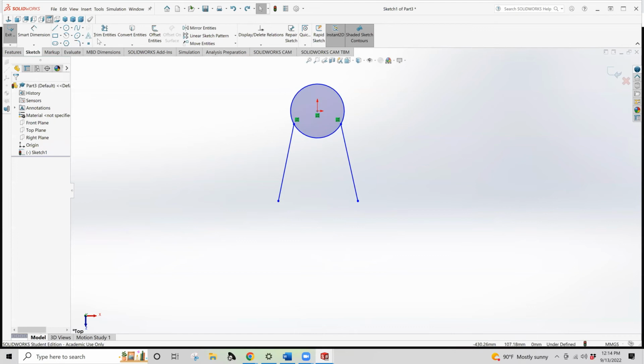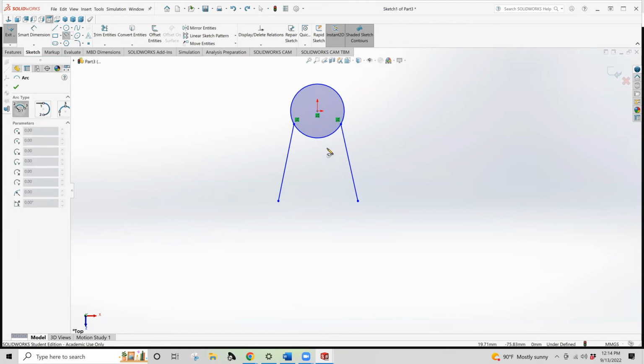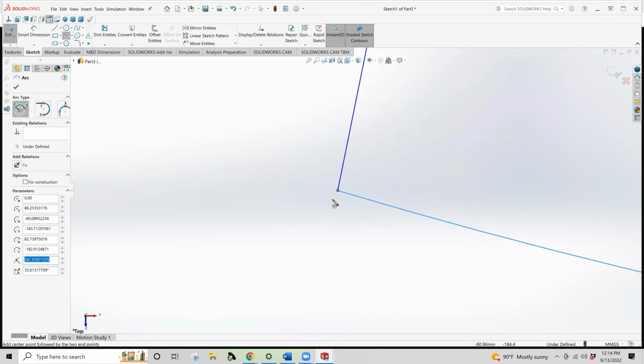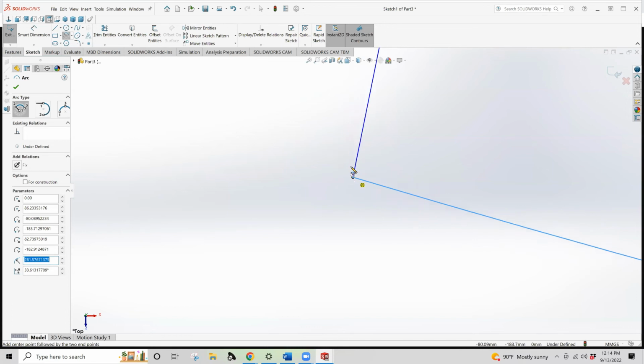You want to undo that arc. And for especially some of the more complicated geometries with broad sweeping arcs that are almost flat, but not quite, you want to put the radius somewhere up here where it's still in line with the origin. You can still have some kind of control over it. But then when you do this, instead of trying to force the arc into something, this point is concentric.